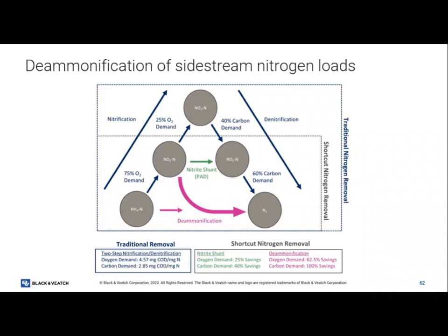Getting back to what I was talking about though, this Anammox bacteria is taking advantage of microenvironments. It's protecting itself in a layer of AOBs, because it does not like that DO. And so it has to take this nitrite and ammonium and make this nitrogen gas without DO and without carbon. That's the benefit. And for how complex it sounds, it's actually a very stable and pretty straightforward process once it gets going.